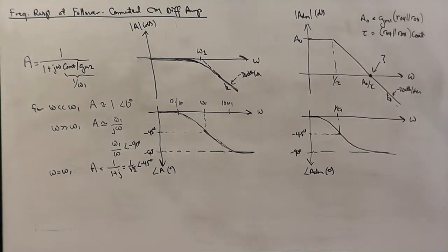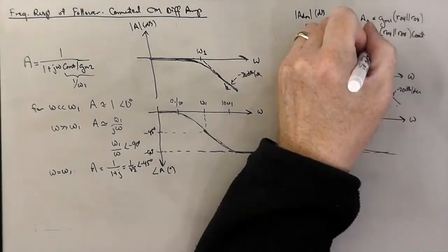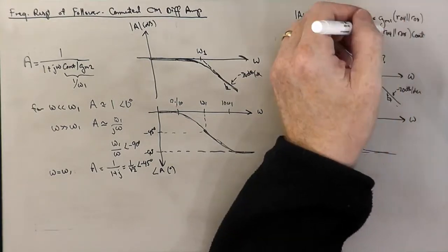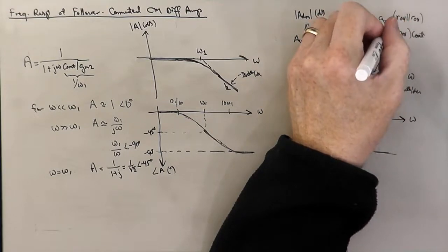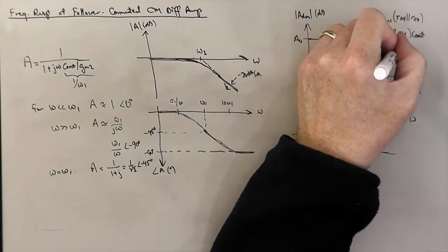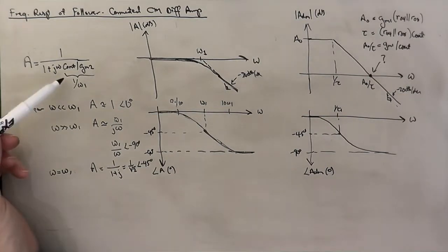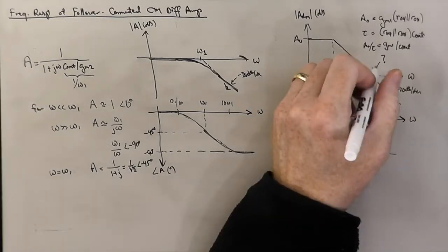Okay? Well, what is A0 over tau? We can just divide these two things. So A0 over tau is equal to, well, the RO4 parallel RO8s cancel, and we're left with GM1 over C out. And if you recall that GM1 is the same as GM2, then it turns out that this frequency is the same as omega 1.